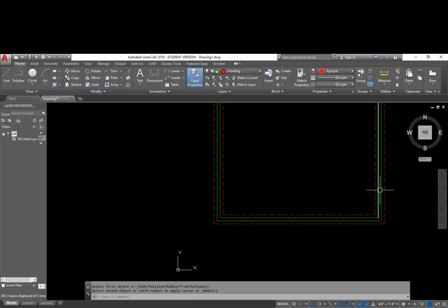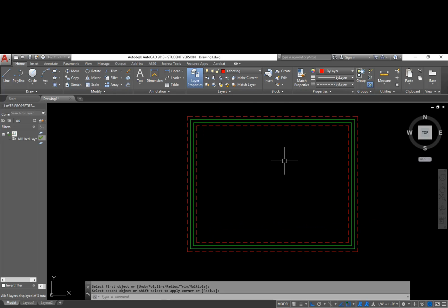And probably what we'll really do is a half course, so that the door opens up level with the slab and the door is still 4 inches above grade. But we have to find the location of those so that we can show it on this plan. So what we have to do is go through and remember what our rules are for using modular dimensions and see if we can make those work the best that we can.